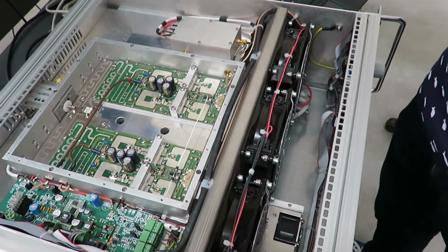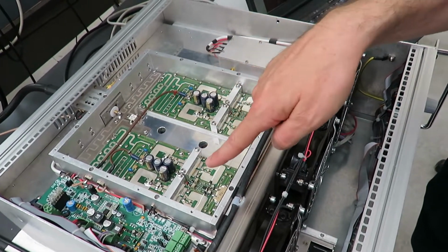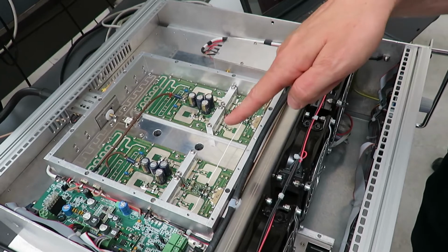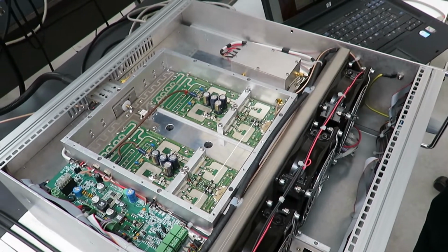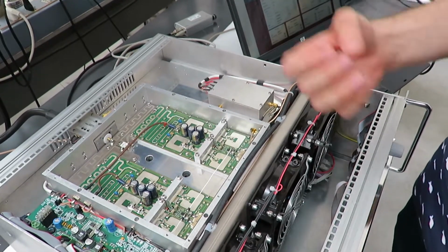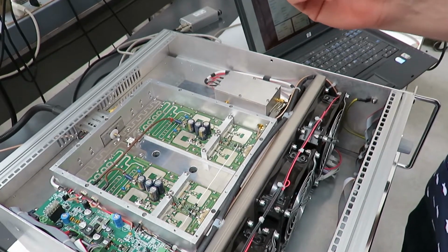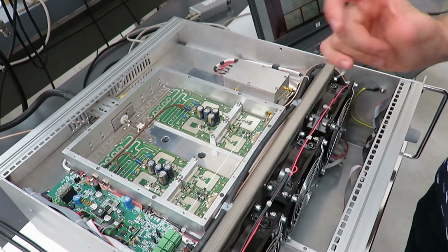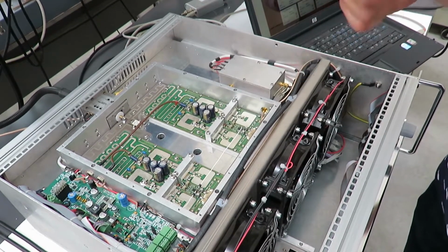Here the technology is totally different. We have two transistors, one operating class C and the other operating class AB. The class AB is operating on the average section of the signal, and so it is always on. The other one operates only on the peaks of the signal, and it is on just when the peaks arrive. And that's the secret behind power saving.